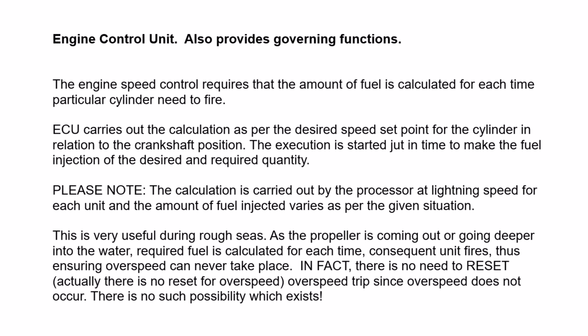Please note, the calculation is carried out by the processor at lightning speed for each unit, and the amount of fuel injected varies as per the given situation. This is very useful during rough seas, as the propeller is coming out of or going deeper into the water. Required fuel is calculated for each unit when the time comes for firing. Each consequent unit fires accordingly, thus ensuring overspeed can never take place. In fact, there is no reset for overspeed, since overspeed does not occur. All right.